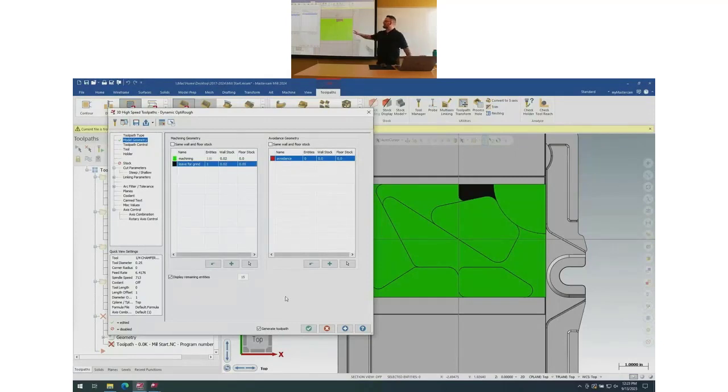And so this will leave a different floor stock than the rest of the toolpath. You can't do that in 2017 because you only get one field to leave stock on the walls and the floors for everything, no matter what you select. So that does limit you. Is there a way around that? Yeah, if you duplicate your OptiRough, you start with what you want for the grind, and then you do your second one when you add an avoidance region. But it's so much more work, right? Like that's what we're getting away from.